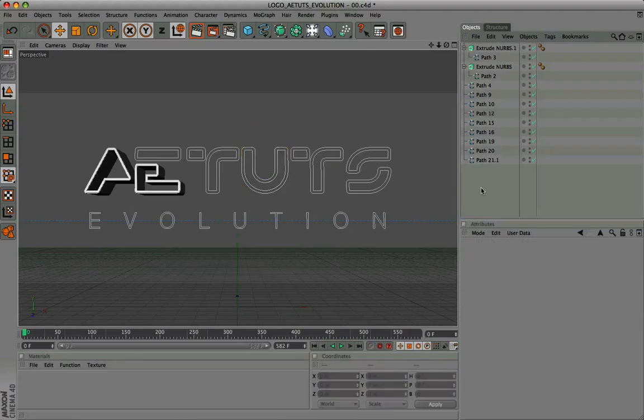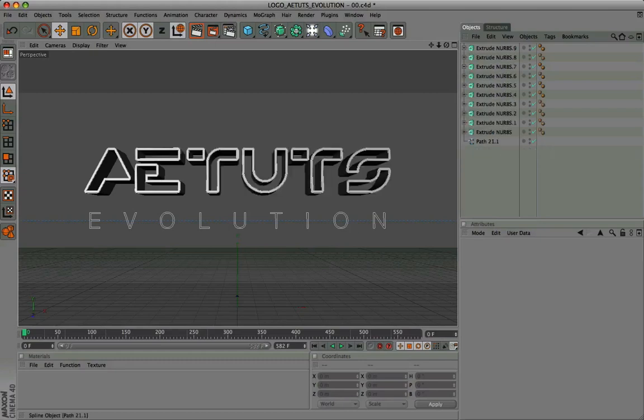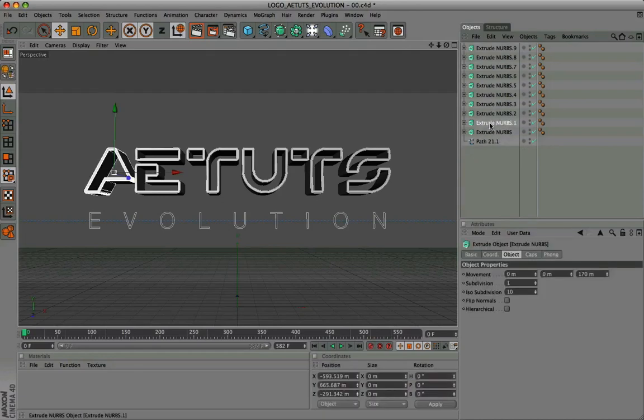It is a fairly simple work that will require a couple of minutes, but give you many advantages, especially during the animation. After inserting correctly extrude NURBS, all the letters and parts of letters, but more importantly after placing the pivot in its axial center, you must rename all levels, so they can be recognized immediately and easily.